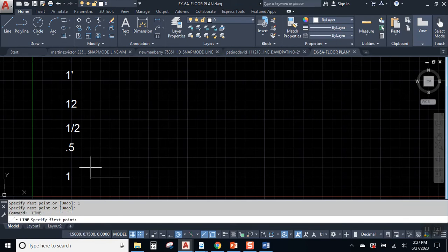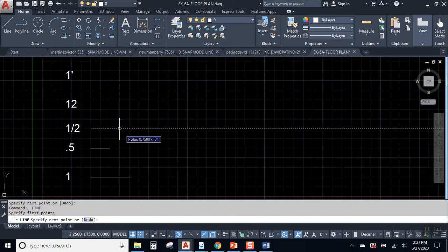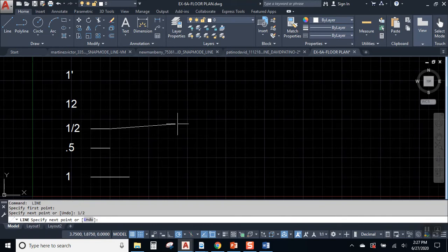And you know, for what we've been doing, it's been working just fine, so there's nothing really to have to unlearn here. I type in 0.5 for a distance, and that is half as long, that is 1/2 inch. And if I typed in 1/2, because you can type in common fractions like that, numerator slash denominator, and hit enter, you also get 1/2 of an inch.